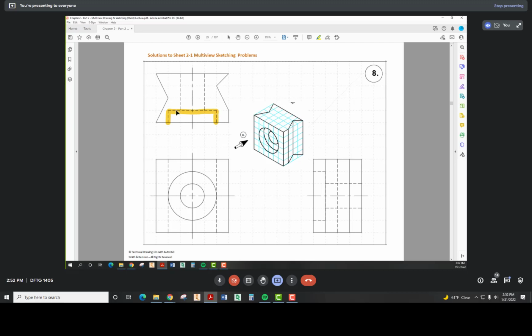This only goes 1 unit deep. But if I drilled this, the first thing I do is drill this hole all the way through. And then I would find the center of that and make this flat bore. And we call it a bore. It's like boring out the center of something, right? When you take an apple core, it's going to bore out the middle of that apple. It's going to go straight through the center and just mill it out or drill it out.